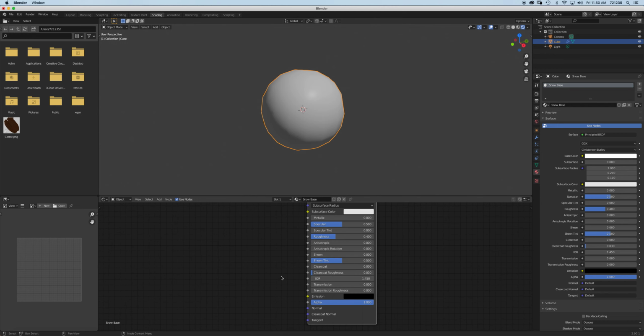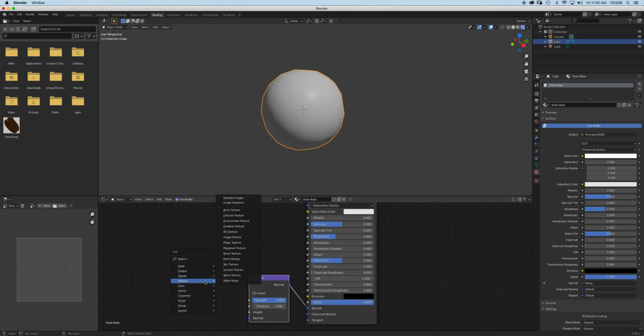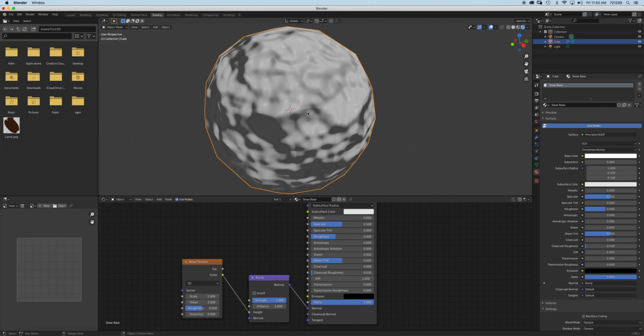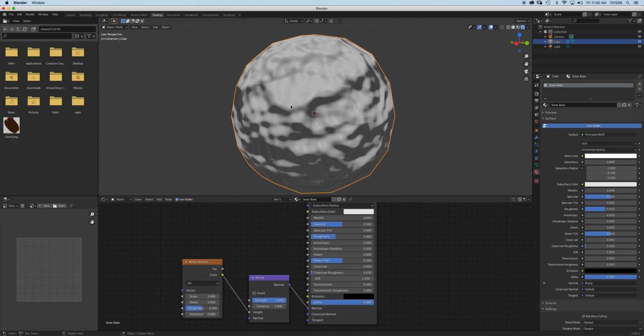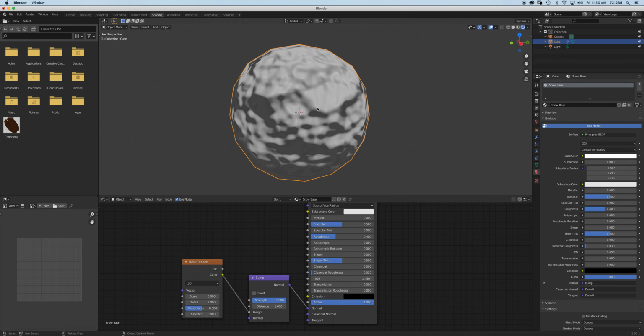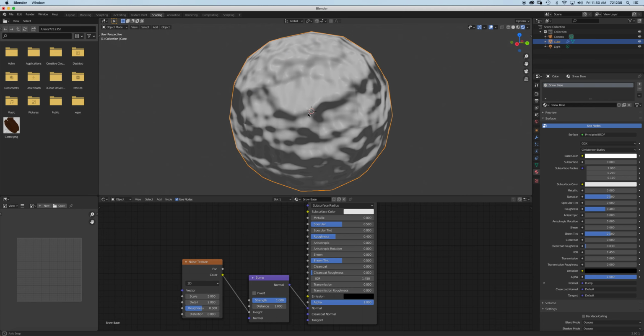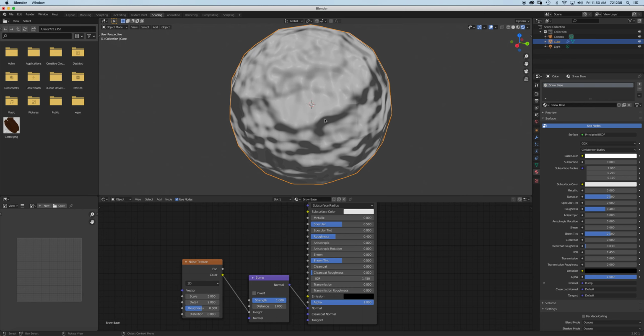All right. And before we start modeling it, we're going to give it a procedural bump map using a noise texture. So I'm going to do Shift A. Let's get the vector bump, plug that to normal. Shift A again. Let's go to texture, and then let's get a noise texture. Color to height. As you can see right here, it applied this noise texture around this, and it's quite huge, it doesn't look anything like snow, so we're going to do something about the detail right here.